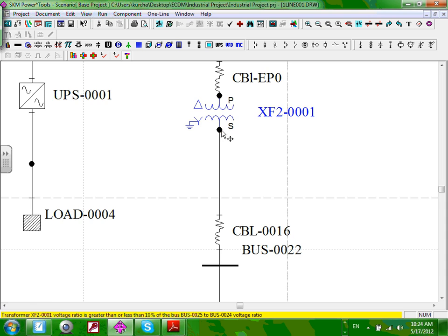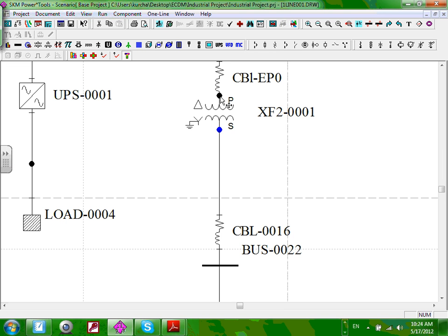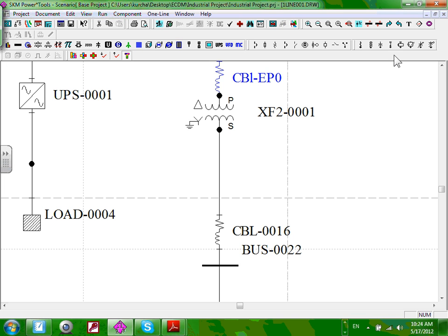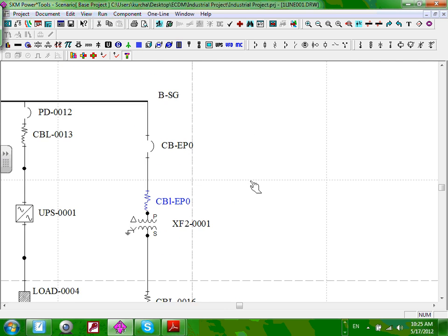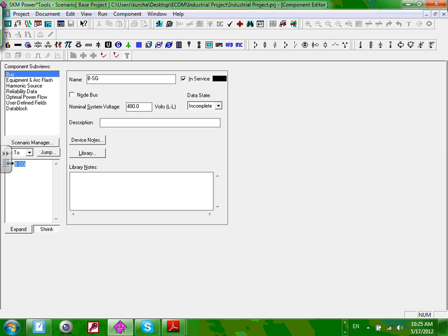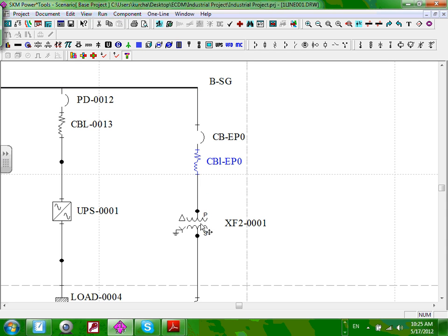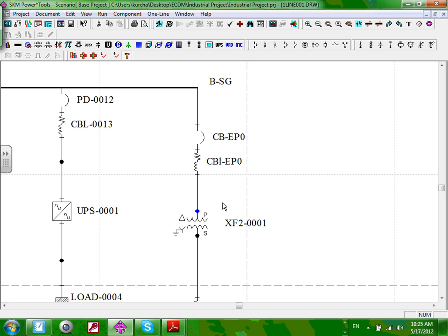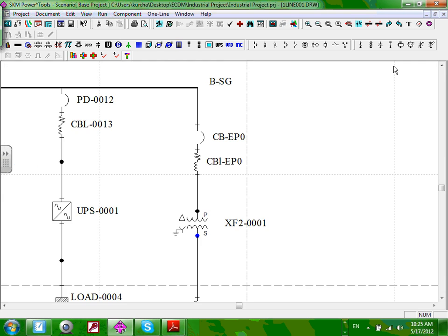So, it's telling me some mismatch in the voltage, 2.8 here. What's the voltage in the primary? The voltage in the primary should be 480. Okay, 480 on this side and 480 from this side, and there you go, 208. So what's wrong with you, buddy, old pal?